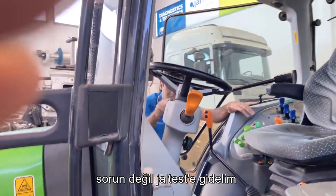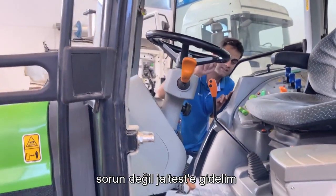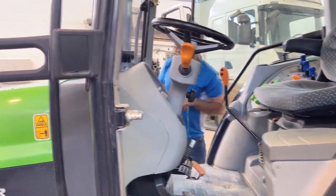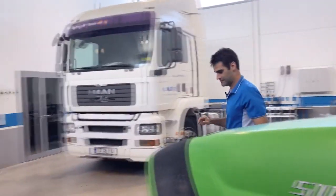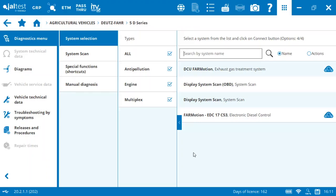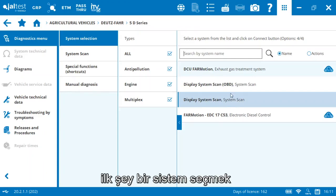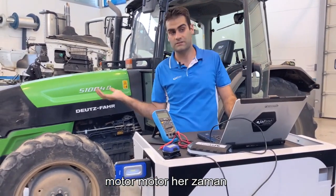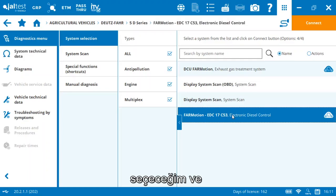I don't know where it is. No problem. Let's go to Jaltest and let's try to locate it using the location pictures. The first thing is to select one system. I don't care. I will select, for instance, the engine. The engine is always in the tractor, so I'm going to select the engine and then connectors.